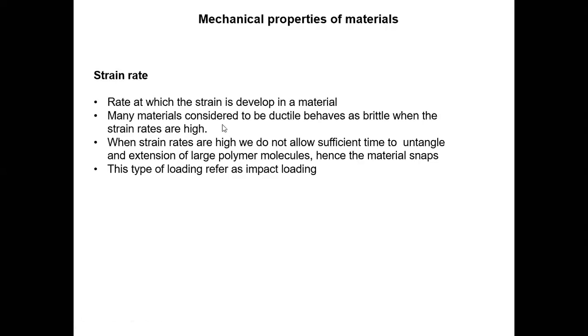Many materials considered to be ductile behave as brittle when the strain rates are high. That means in some materials, the strain development is quite fast, so even if the material is ductile, it can behave as a brittle material.